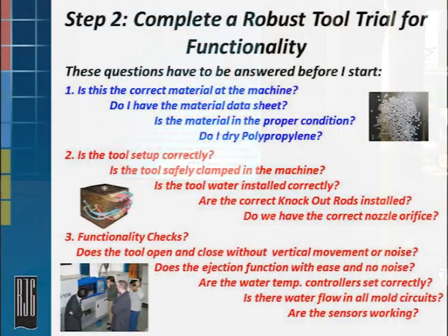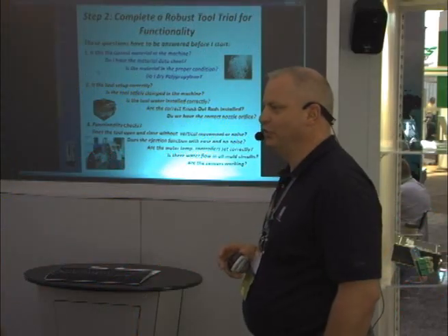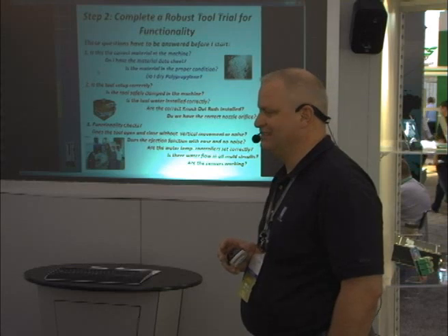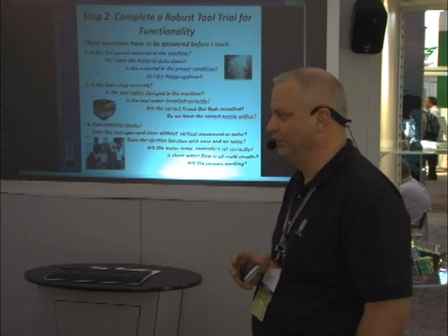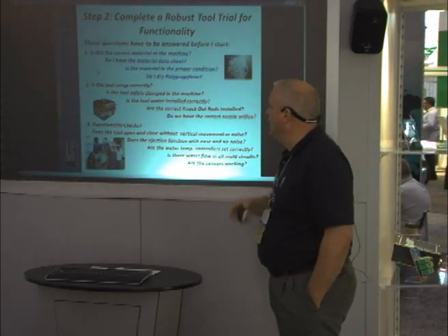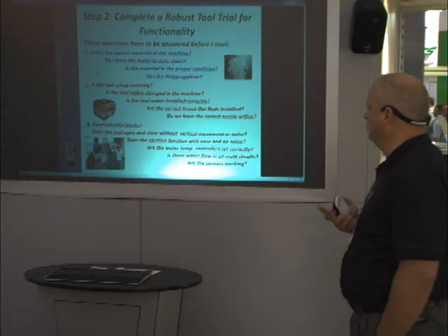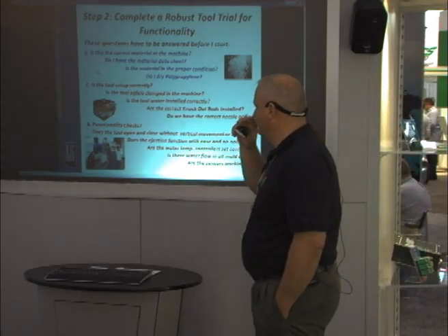Is this material in the proper condition? As you notice, I put up there, do I dry polypropylene? Well, maybe some people aren't drying polypropylene, but there are a lot of people in the industry today conditioning their polypropylene to a specific temperature. It's not necessarily drying, but I need to know that I'm bringing that material in and I'm putting it in the proper condition.